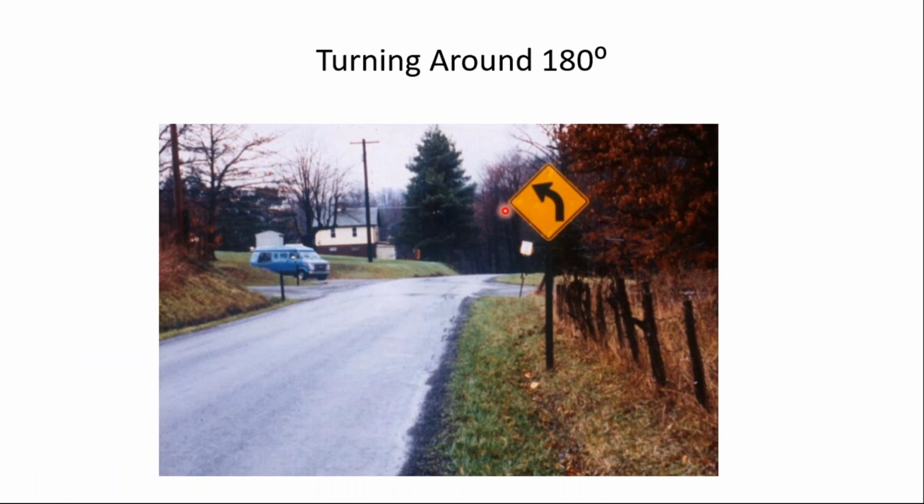Notice there is a left curve warning sign, no advisory speed plaque though. And I think you can see, maybe see the start of the curve here. The curve does go to the left, but notice because of the terrain or the dip in the road there, drivers can't really see the curve alignment, at least from this point on the roadway. And again, remember, at the time of the crash, there would have been some large maple trees around that curve.